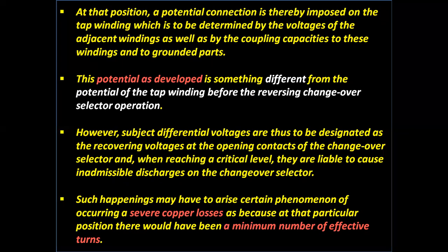However, such differential voltages are designated as the recovering voltages at the opening contacts of the changeover selector, and when reaching a critical level, they are liable to cause inadmissible discharges on the changeover selector.